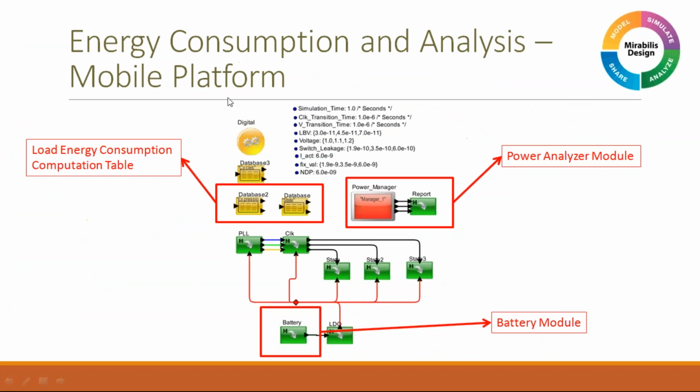Okay. So looking at the energy consumption and analysis for a mobile platform, here we have an example with an abstract level model of a mobile platform with PLLs and processors and modem and things like that. In this case, we are actually computing power consumption based on the leakage current and voltages and fluctuations in the voltages using expressions. And we are not really relying on the state of that particular component based on how long you're running or how long you're processing in the platform itself.